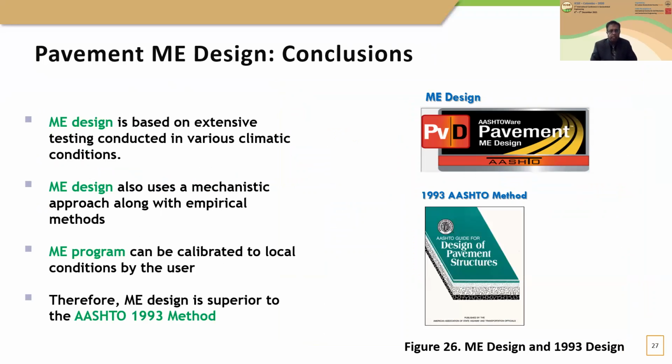In conclusion, it is obvious that the ME design is superior to the 1993 AASHTO method because it is based on extensive testing and research conducted in various climatic conditions. It uses a mechanistic approach along with empirical correlations, and the program can be calibrated to local conditions by the user if necessary.